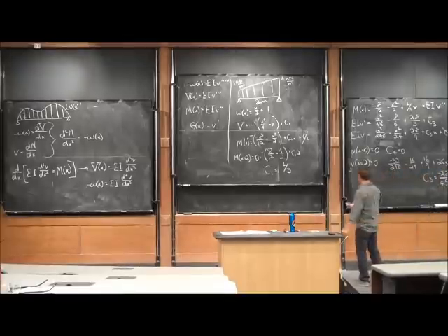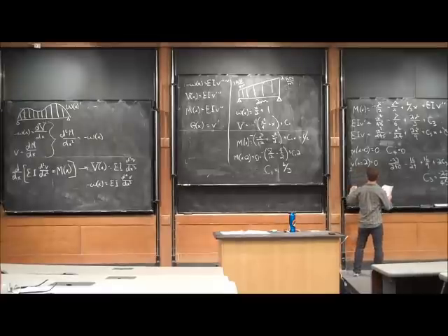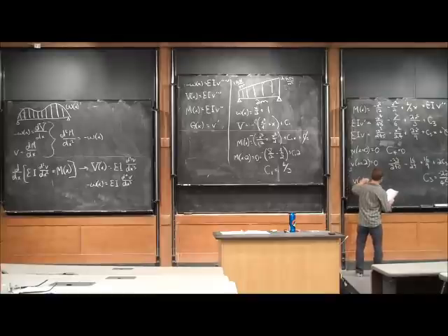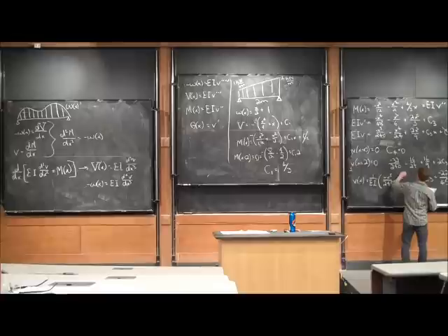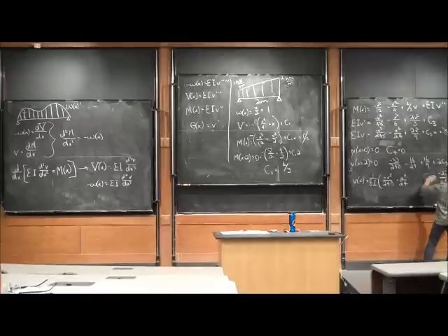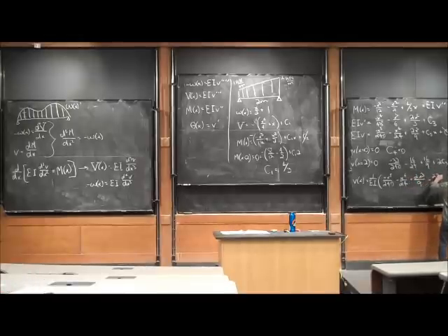So, that's all well and good. What does that end up getting us for our final deflection equation? Our deflection as a function of x is going to be equal to negative 1 over EI times negative x to the 5th over 240 minus x to the 4th over 24 plus 2x cubed over 9 minus 22x over 45.